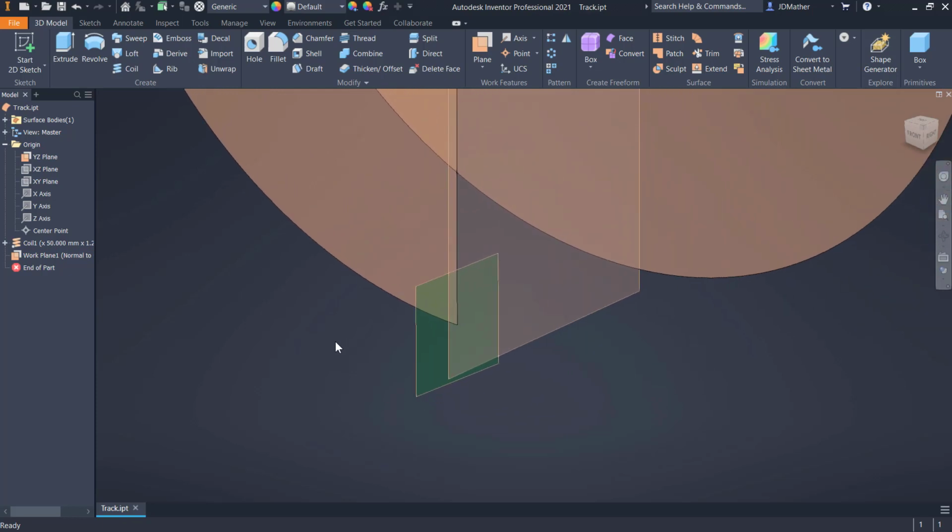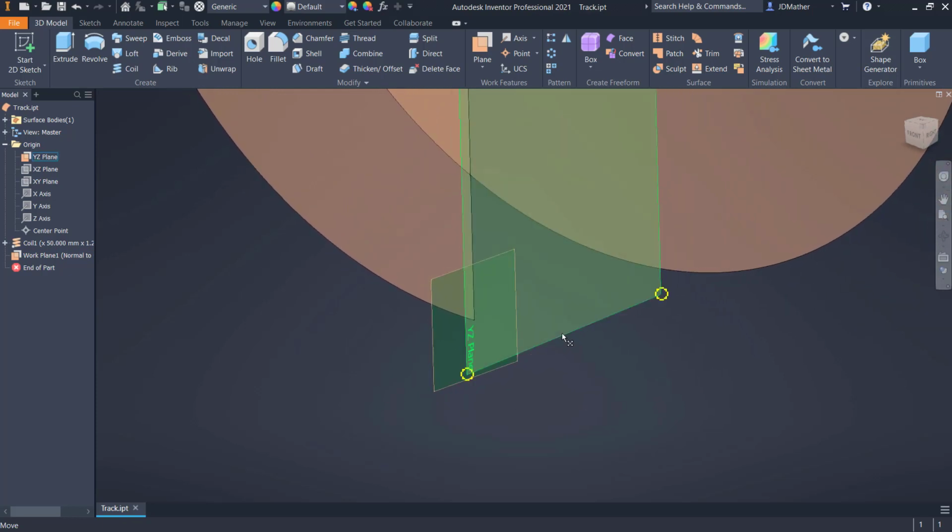So I see beginners a lot of times will start a new sketch on this plane, but it's not perpendicular to this path. And if we had just done this as a solid coil, the same situation, they would start on this plane, but that plane, the YZ plane, isn't perpendicular to this helix. So we needed to create this plane perpendicular to that helix. I'll turn off the visibility of the YZ plane.